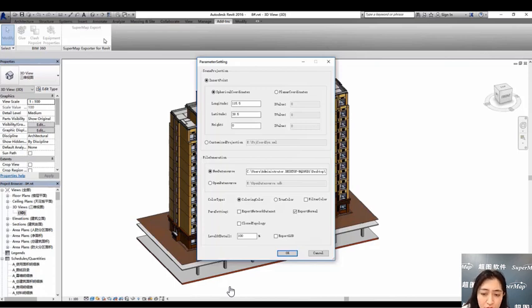When the spherical insertion point is exported, the coordinates of the insertion point are in the latitude and longitude coordinate system. If you use planar coordinates, it will import by x, y based on the planar coordinate system, and the base point must be 0.